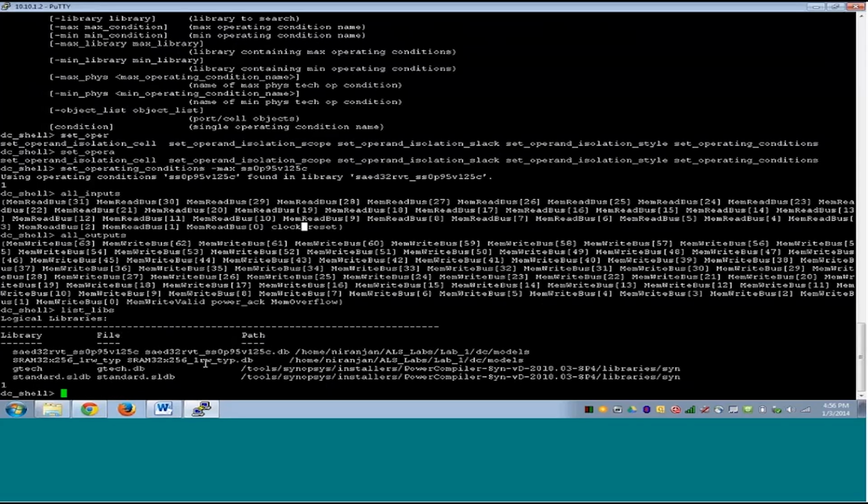I'll try and get a list of buffers and make sure that the outputs of my design are able to drive a load that can be driven by the buffer of the maximum size. If not maximum, then very near to maximum. Let's first see the list of buffers in the design.